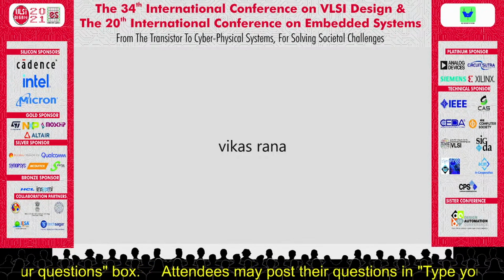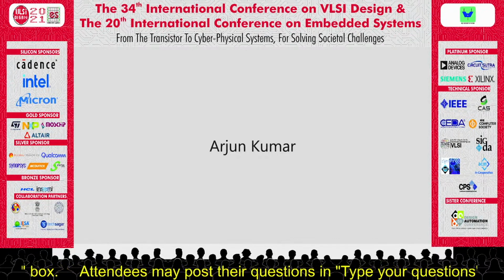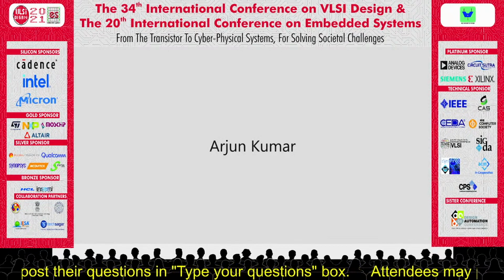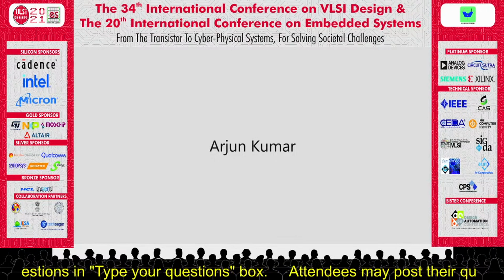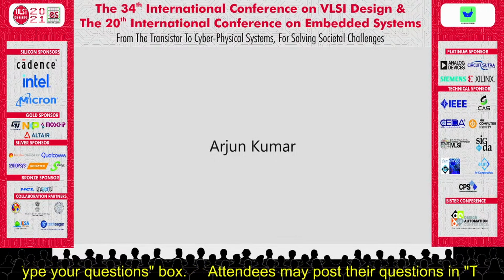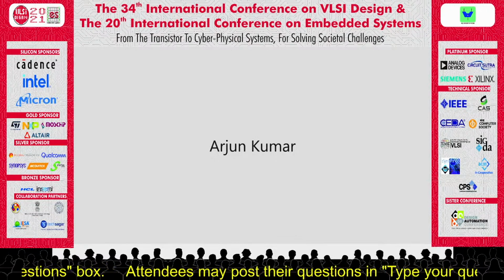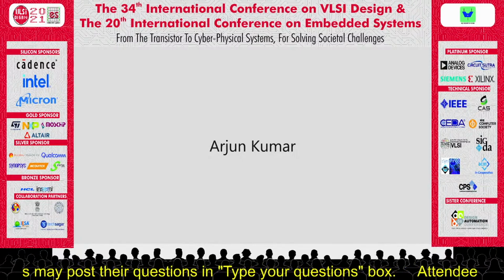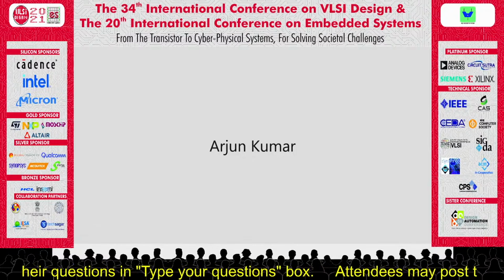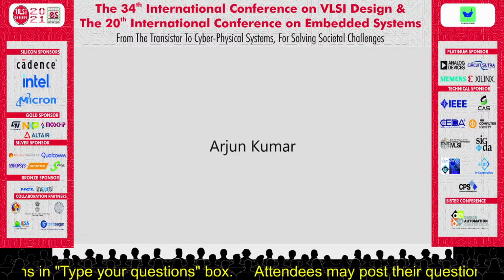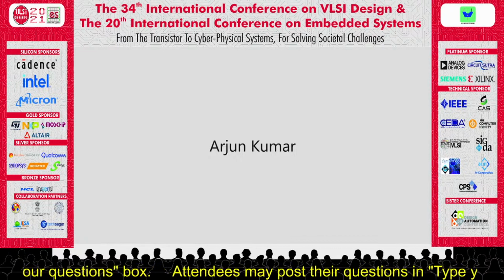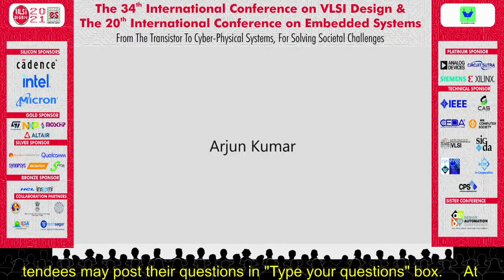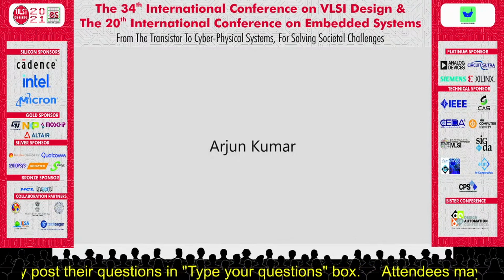Thank you, Vikas, for a very good question. In MoS2, DIBL and all short channel effects will be there, and the value of DIBL is found in the literature. Our work is not focused on the short channel, but in our previous paper we studied those parameters. DIBL is smaller compared to silicon, and a silicon MOSFET is very difficult to scale down to 1 nanometer. But with CNT and MoS2, it is possible to get an on-off ratio of the order of 10 to the power 5 even at a 1 nanometer channel. That is not possible with the silicon MOSFET.